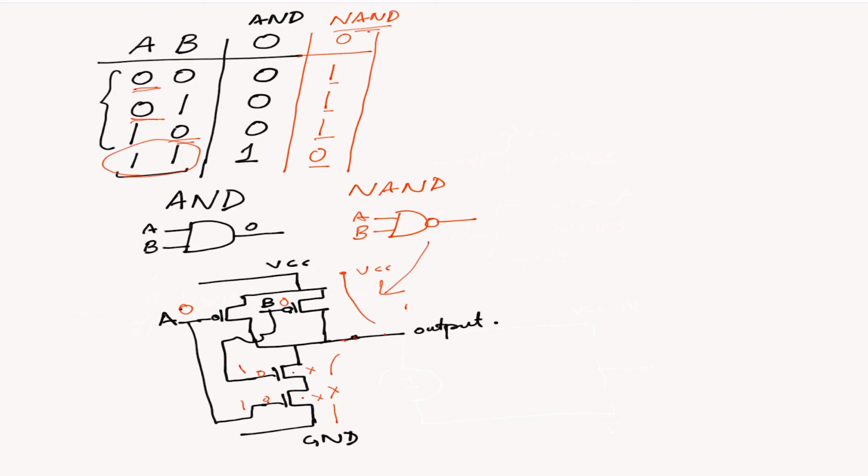Typically in physical design, a big block consists of so many transistors, several hundred thousand, more than a million transistors. But we count the overall design size in terms of gates, and typically the NAND gate is used as the standard one.